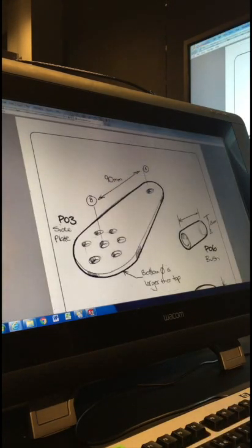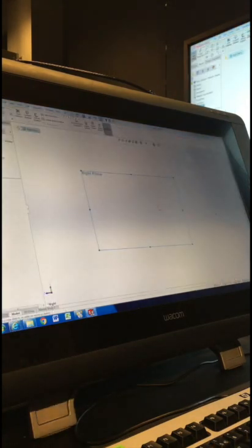So let's select the right plane to sketch on. So click on the right plane and then click New Sketch, and it should take you to the right plane like this. Now, our very first step is we're going to build 2 circles. Okay, sketch 2 circles. So we're going to do a large one at the bottom and a smaller one at the top. The large one at the bottom needs to start on the origin. That's going to be our sketch segment that's referencing the origin.